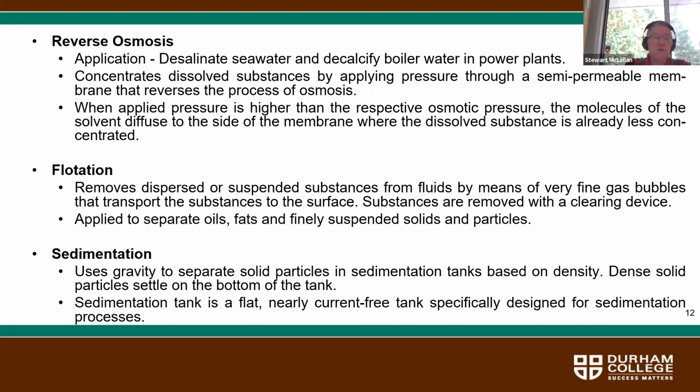So usually when tanks are used for the sedimentation, they're usually very large structures. And the reason for that is because you essentially need to have a close to laminar flow through these tanks so that the particles will actually settle.